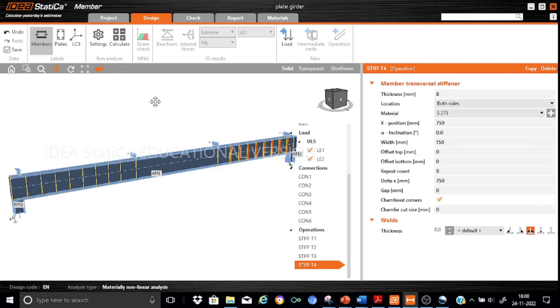One, what we normally call the MNA, that's the material nonlinear analysis, and the second one is the LBA, that's the linear buckling analysis. This analysis will take some time. I have noticed they take almost as much as 30 minutes on my laptop. So I'll just proceed to showing you the salient results of the developed model.